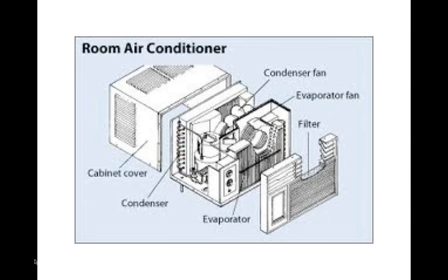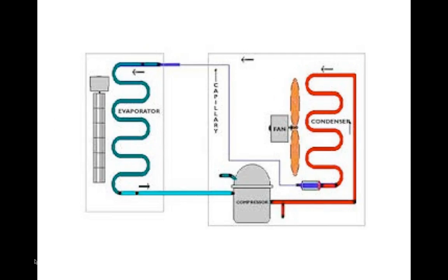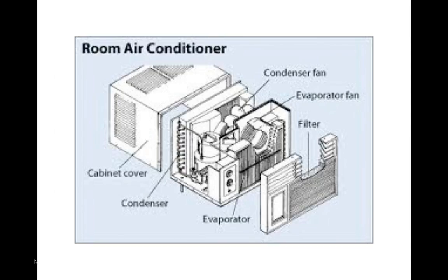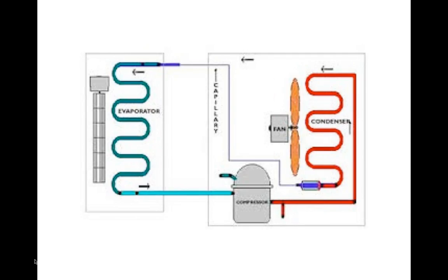Now, to talk about how refrigeration units work, a lot of you have window unit air conditioners, and the way that they work is they use a Freon refrigerant, and that Freon refrigerant is metered into a coil. If you look at this, the right side is the front of the unit, which is inside the house. The left side is the back of the unit, which is outside of the house. You see a fan there, you see a condenser and evaporator. Those are two coils. I'm going to show you those two coils here. There's the condensing coil and the evaporator coil. Unfortunately, here they're reversed. The inside of the house is on the right.